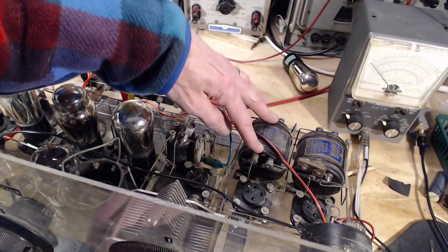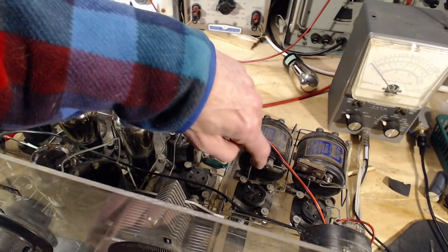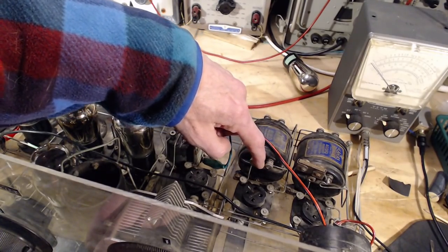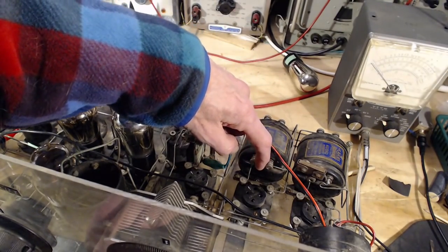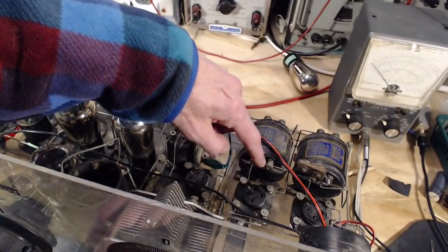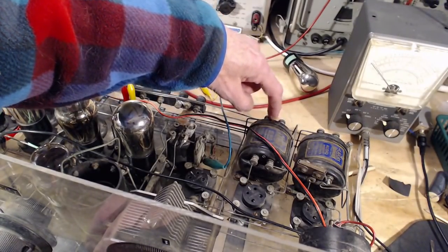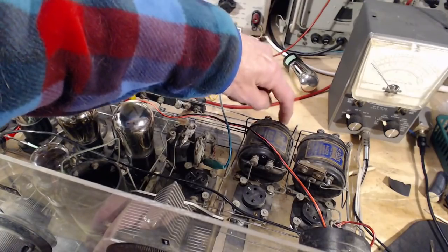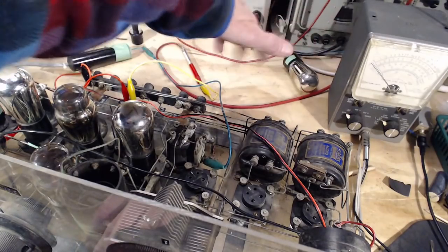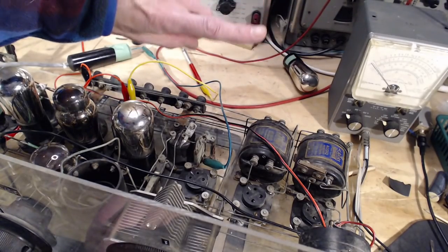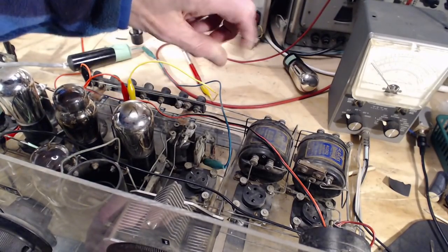These are amplifying transformers. So the secondary I was able to measure at 5, 6, 7 thousand ohms. And I think they multiply by 5 or so. So could I just simply say 5,000 ohms here is probably going to be 1,000 ohms here. If I put a 1,000 ohm resistor in here, I'll be able to energize the plate on this tube. I don't really care about the output, I don't really care what happens to it, not at this point. It would be sitting on this resistor, but really I want to listen to the grid.